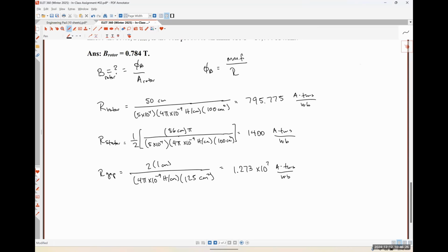About 1 million times larger, right? Pretty big. So for a lot of rotating electrical machinery, if we build that machine out of ferromagnetic material, which has a very high permeability, the only reluctance that's actually going to contribute to anything is the air gap itself. That's actually how they design reluctance motors, which are the new motors that are used in newer Teslas.